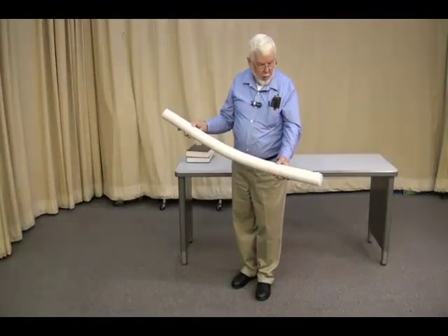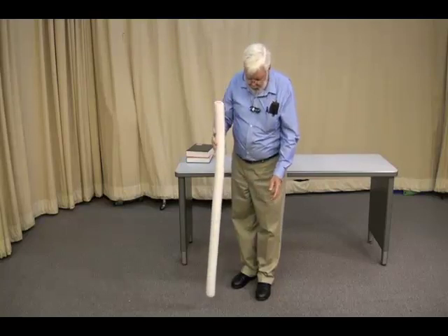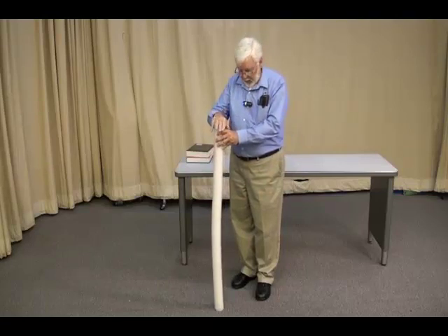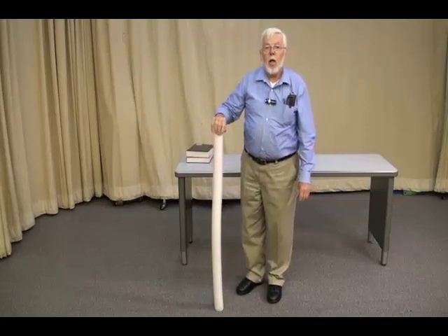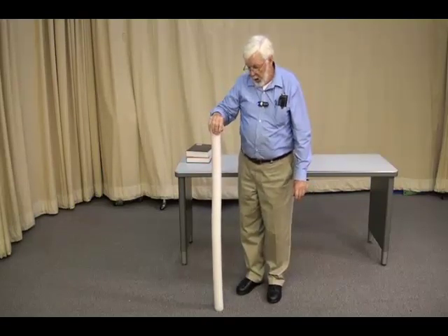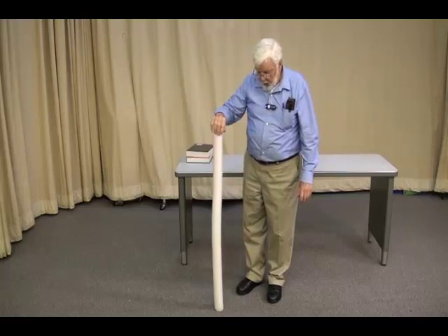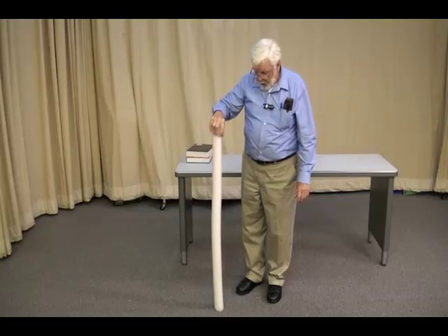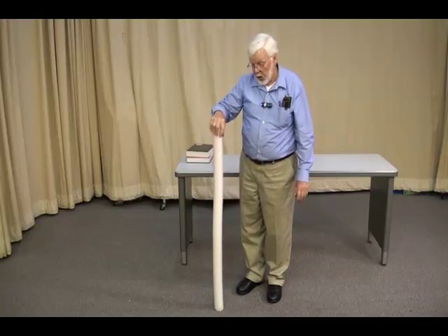Okay, I have here another noodle, longer than the other, made of the same material. And I'm going to use it, in this case, as a column. So a column is used to hold something up. And if the column is relatively long versus its diameter or its dimension, then it's called a slender column. And we have something called a slenderness ratio that we can calculate to determine whether it is or is not such an animal. And the problem with this is when it fails suddenly and catastrophically.